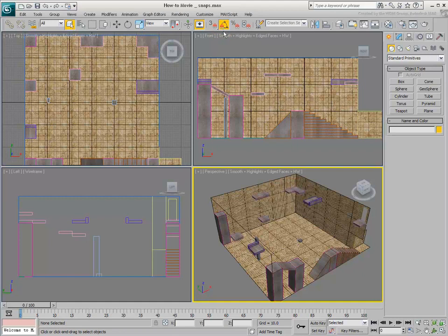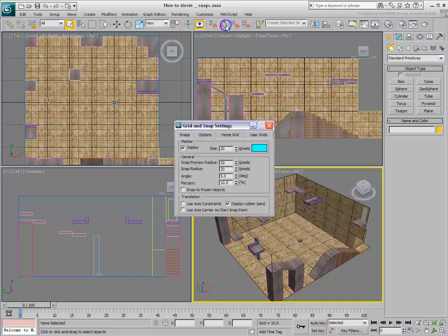The default hotkey to toggle Angle Snap is A. With Scale, % Snap lets you scale objects up or down by 10% increments. The default hotkey to toggle % Snap is Shift-Control-P. The default incremental values for rotation and scale of 5 degrees and 10% respectively can be changed by right-clicking the rotation or scale snap buttons.